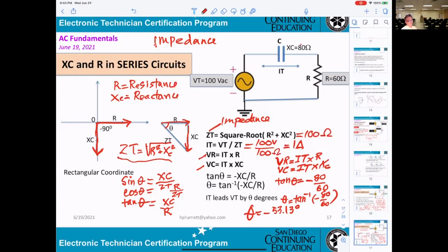That's just like the formula. If you get along with that, the course will be very, very simple. Not like electronics, not like digital. It's very basic for AC circuitry. Okay, finally, the phase equals minus 53.13 degrees. That means the phase difference between the total current and the total voltage. In this case, the total current will be leading the total voltage by 53.13 degrees.